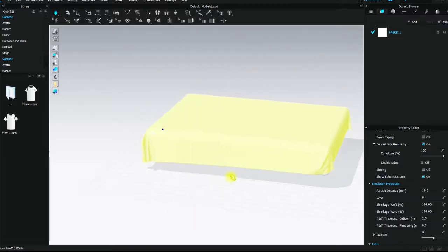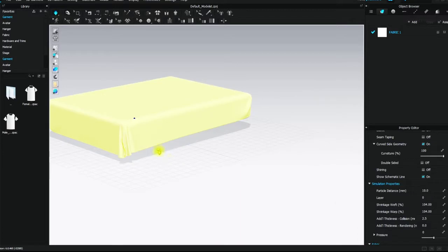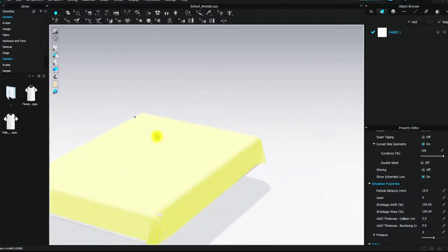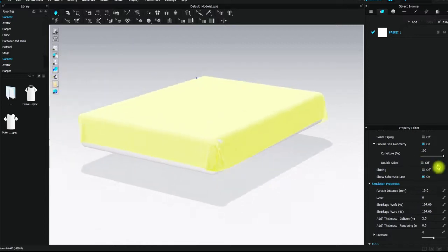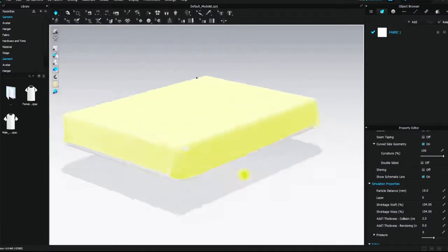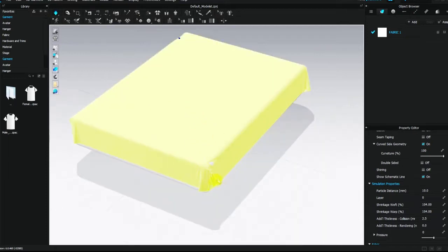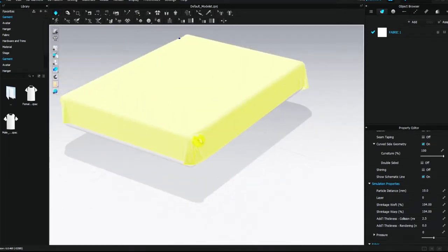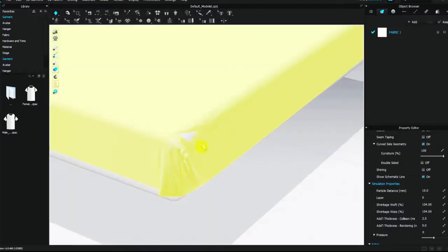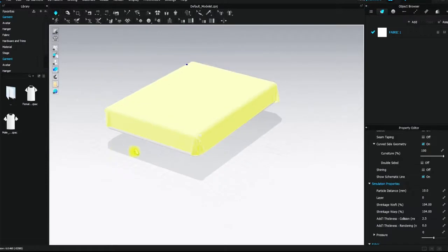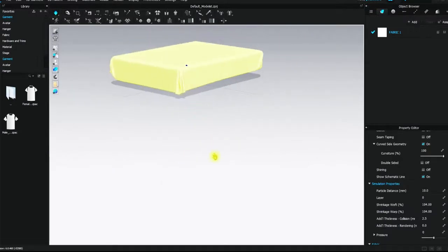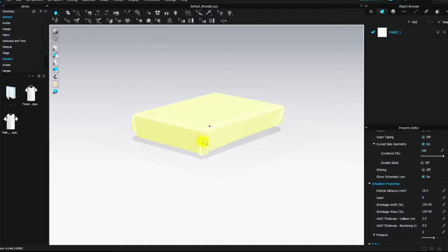All right, so you can see it's still simulating, but you can notice that the detail on the artifact has reduced a lot. If I reduce this value, I have more detail, and this corrects that, but it's still going to take a longer render time from me. So I don't want that. So what I will do is just look around and finish up this mattress, stop this, and try and do the pillow. So once I have this set, I think this is fine right there.